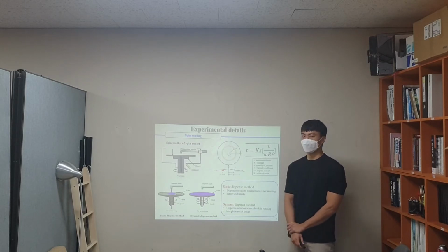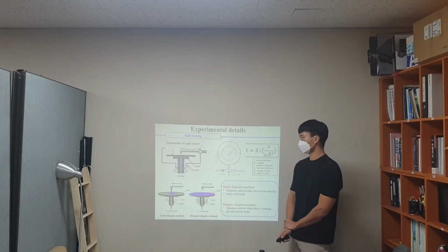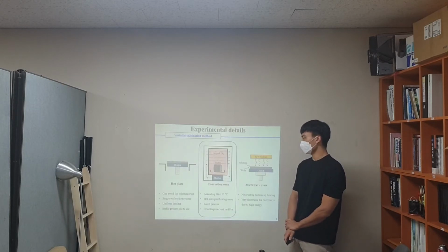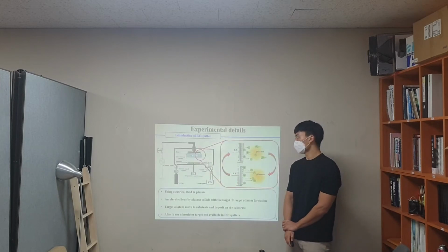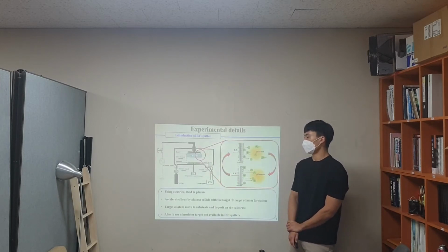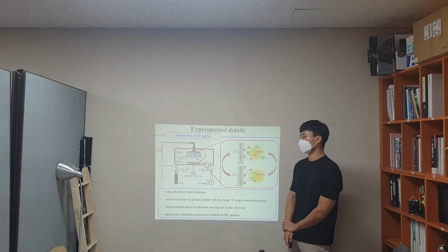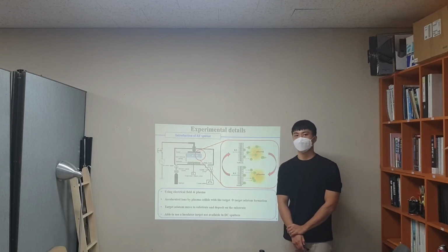To make the device, we use spin coating for the photoresist coating, and then we use a convection oven for baking the sample. And we also use RF magnetron sputtering to deposit the IGZO channel and tantalum oxide dielectric.